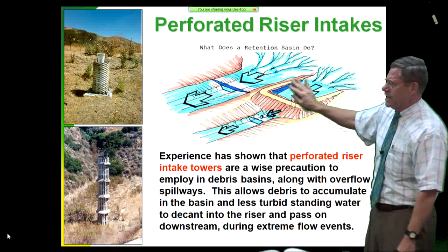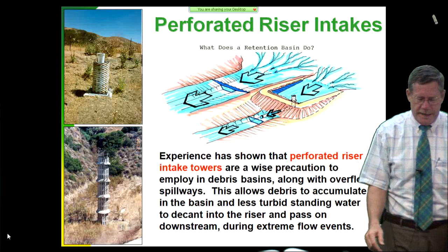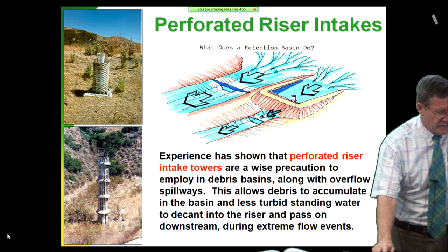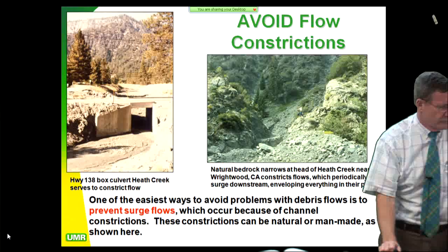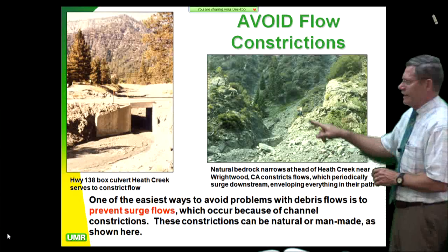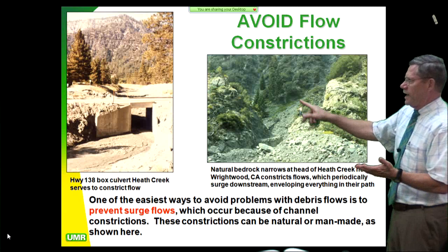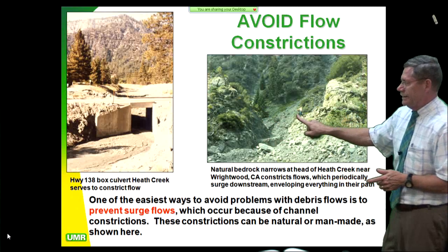And you also are taking the silt, a lot of the silt, out of the bed load, out of the channel. That's real important if you have debris flows because they have such a huge sediment load. Biggest thing is avoid flow constrictions. Here I am standing at Wrightwood. The whole problem at Wrightwood is this flow constriction right here. They have a bedrock narrows there.